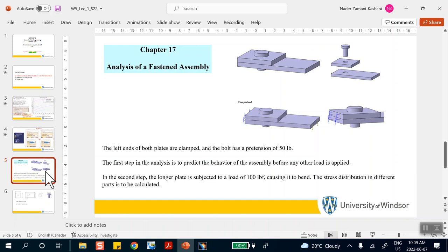One thing you should keep in mind is that if you have a bolt, never cut through it. Because if you look at this problem, you might tell me, didn't we learn all about symmetry, that there's a plane of symmetry cutting all the way through it? Yes, but that will cut through the bolt, and we don't want to do that. Never cut through the bolt.